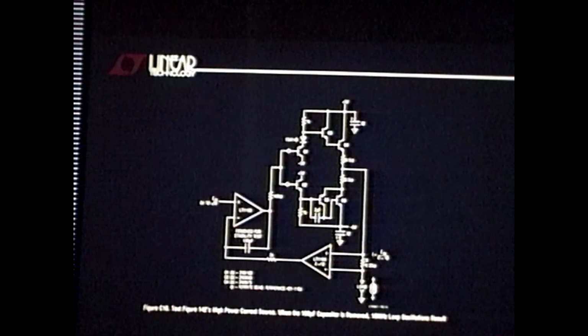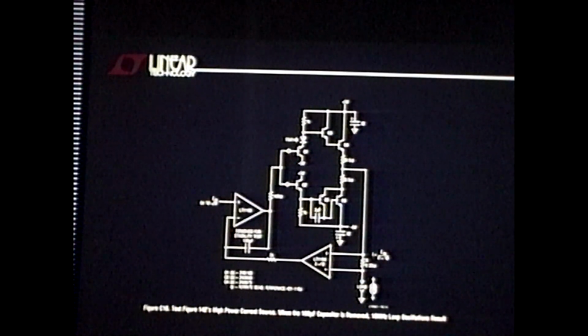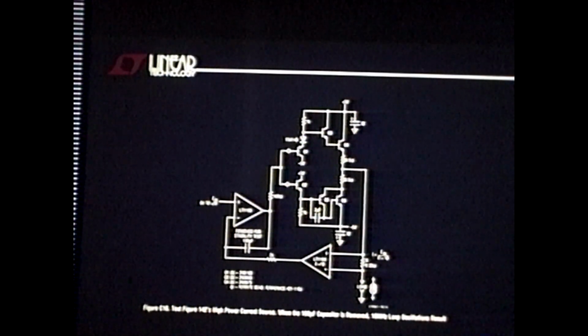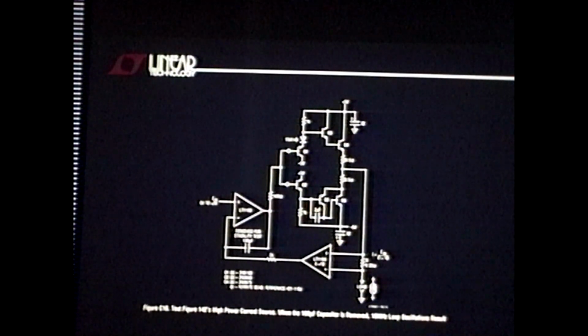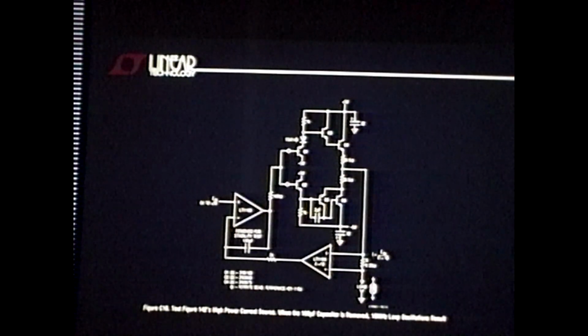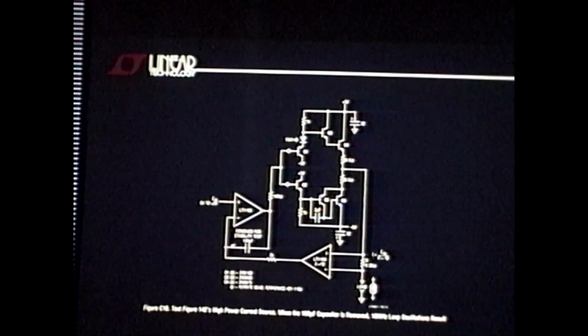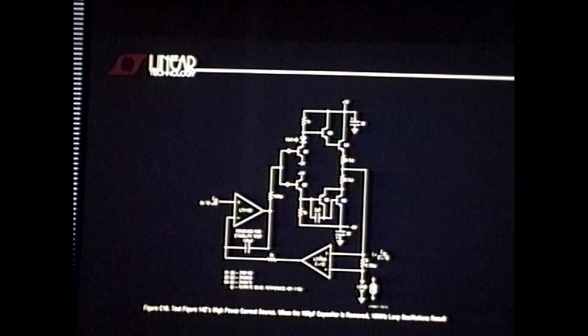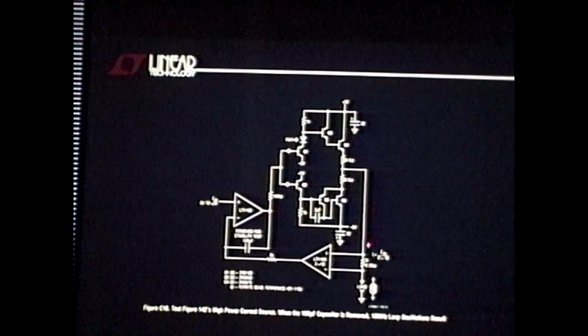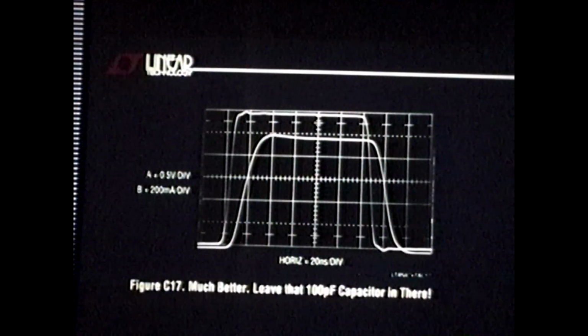Now, remember this circuit? This is the same circuit with the high power 1 amp booster stage in here. So now we're really going to commit suicide. We're going to take the cap out like we did in the last example. We're going to have the phase of the diff amp in there, the lag of that, and the lag of the booster stage.